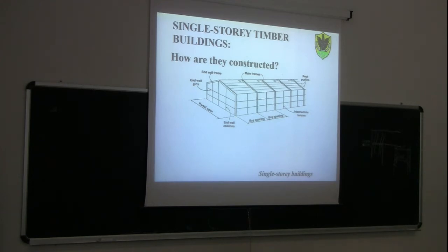Yes, if these girts and columns, yes, columns, this one, can be changed with panels with plywood. Or no, even with plywood, we need those girts because usually the plywood panels come in a very small size. So we're talking about 1.2 meters by 2.4.